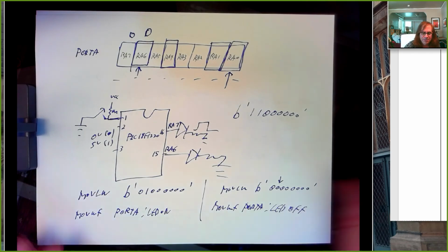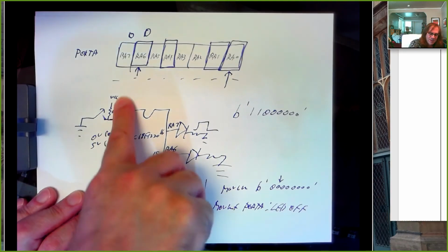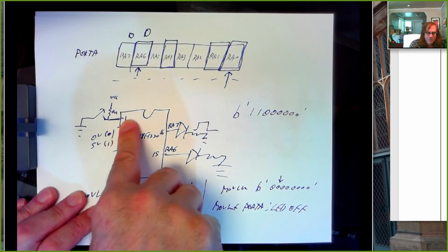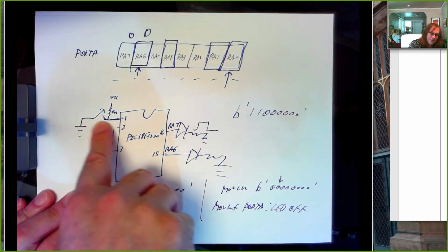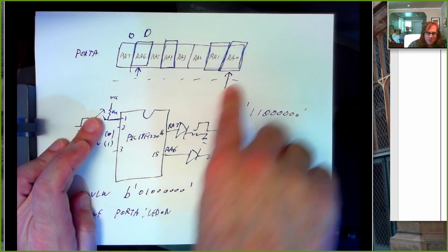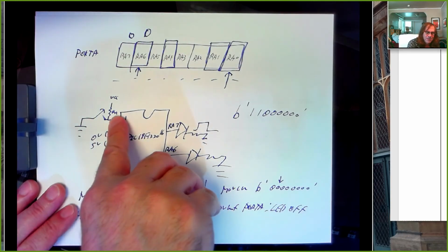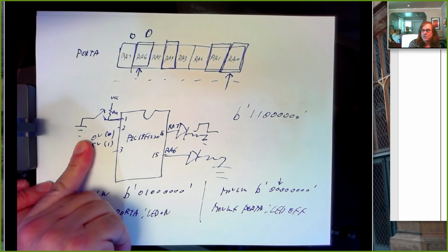But if I write a 0 out to this pin, but I've got this pin connected to 5 volts, is that a problem? Maybe. If I've got this switch closed, so this is connected to ground directly through a switch, and I write to port A and there happens to be a 1 here, which makes this pin 5 volts, I've got a short. I've got 5 volts coming out of this pin going to ground. I'm going to burn something up.